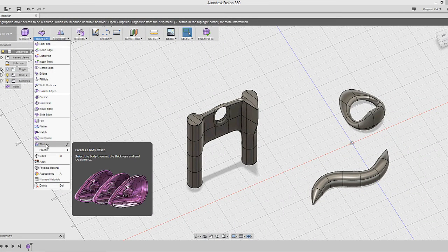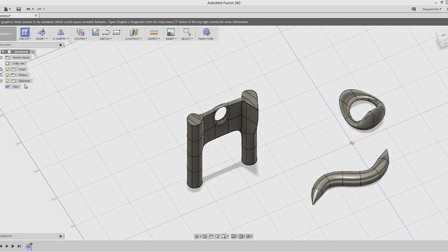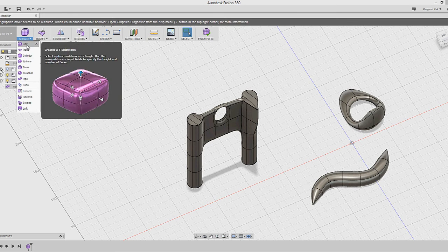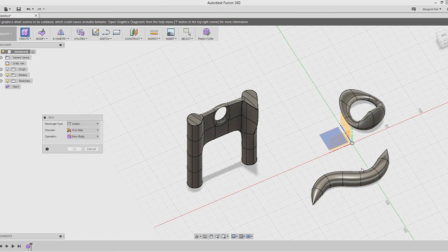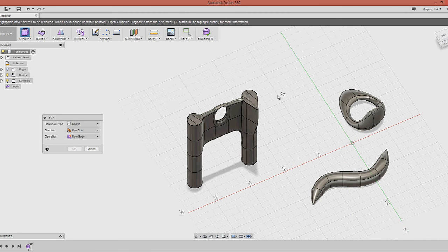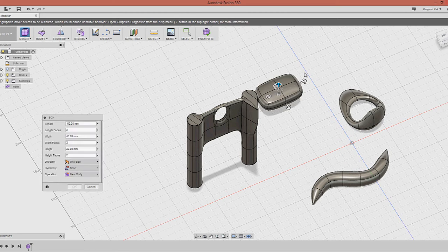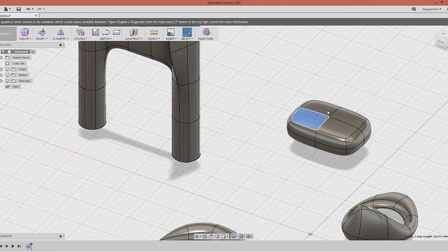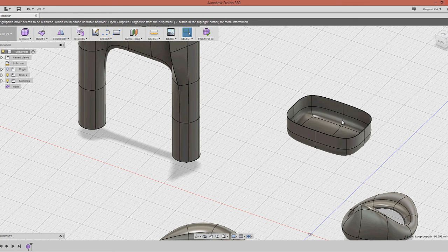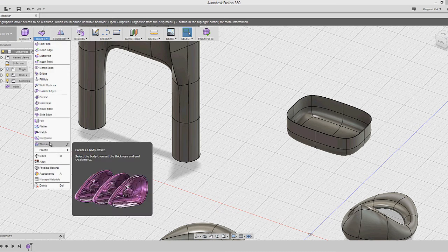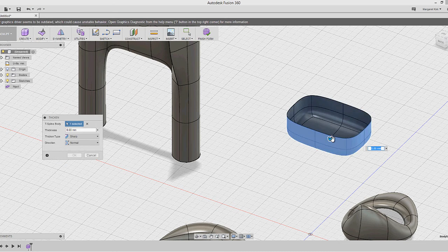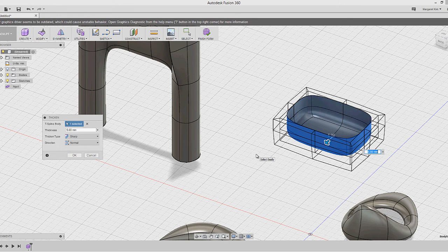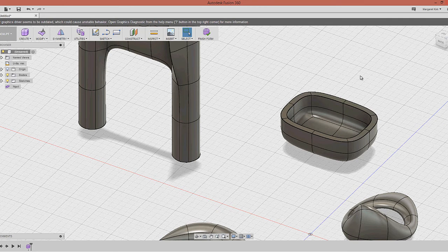The one thing to note also is the thicken, and that's if I essentially have, let's create, we could actually create a box. Create a box on this plane. Okay, I'm going to hit OK to set it. And if I start to delete these faces, what you'll see is that it's basically an empty shell, right? And so what I can do is use the thicken in order to select that box, hit enter, and I can give it essentially a thickness and a shell.